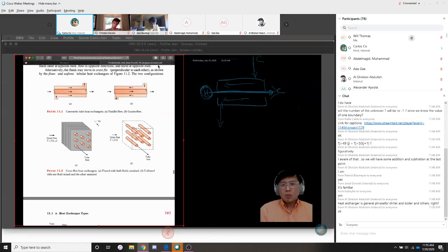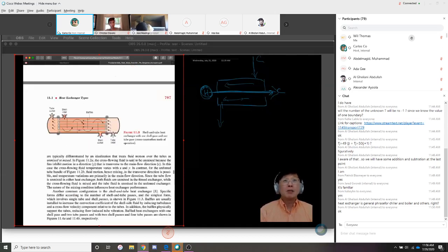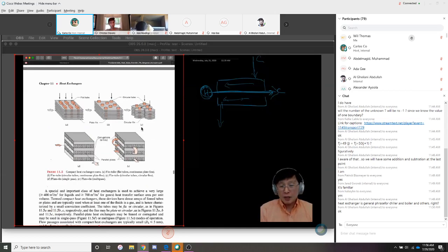You would also have seen situations like this. You basically have tubes, let's say with the hot liquid, and these will have fins on them. The purpose of the fins is to increase the surface area so that you can pass another fluid, often air, across it and have more surface area for heat exchange. So this is a so-called mixed flow or cross flow type heat exchanger. The variety of designs is limited only by your creativity. Here are some more types of heat exchangers.